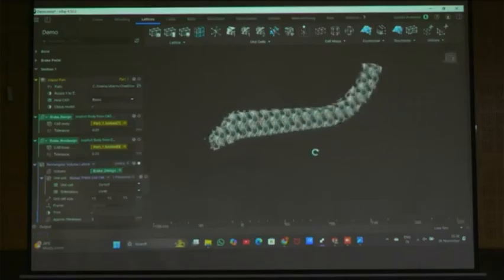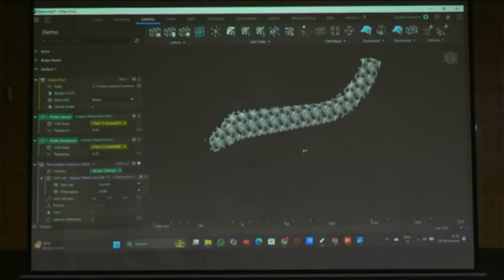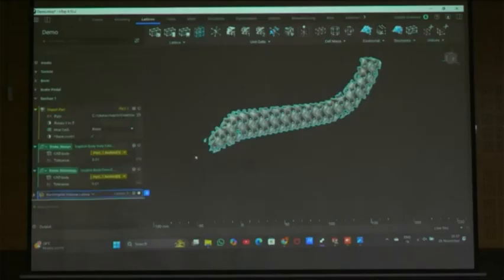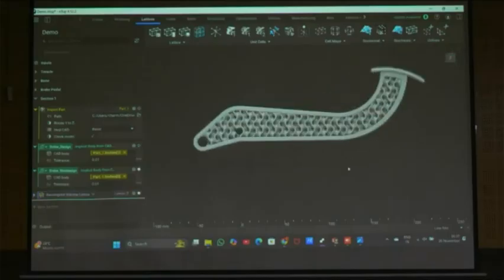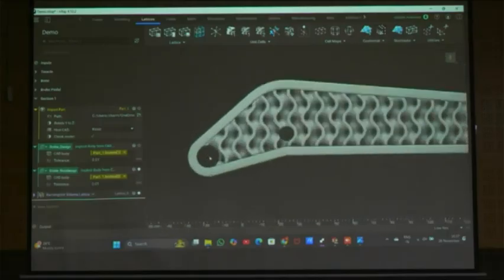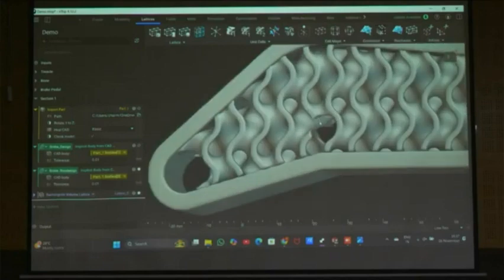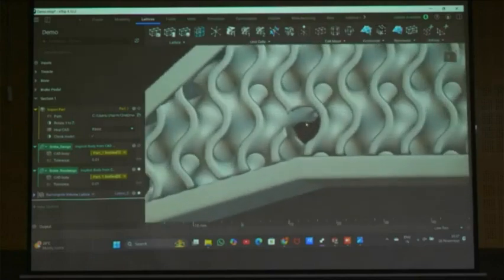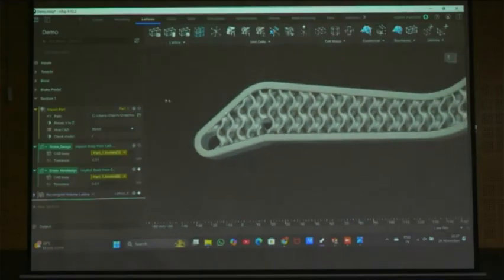See, this is how we can get it, but here the problem is that my intention is to complete the body. I can get the design, and I can combine this with the non-design. Finally I will get this, but here one problem is there. Can you see? See here, this is a good thing, and here a surface is there. Suppose I am applying a bolt, will it fit? There are no threads. So that we need to define as a non-design space. How to define: we will see the Boolean intersect, here only it will come.